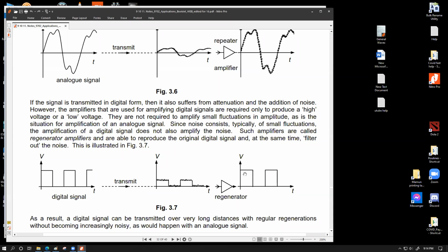So let's say we set up the op amp to have a lower threshold of 0.11. 0.11 means any voltage value higher than 0.11 will be given the full output voltage. Any voltage input lower than 0.11 will be given 0. We can design an op amp circuit like that. Basically, a regenerator circuit works in that manner. It takes the input from the received signal and regenerates the entire signal from its own voltage supply. So this basically makes the entire noise pickup gone.